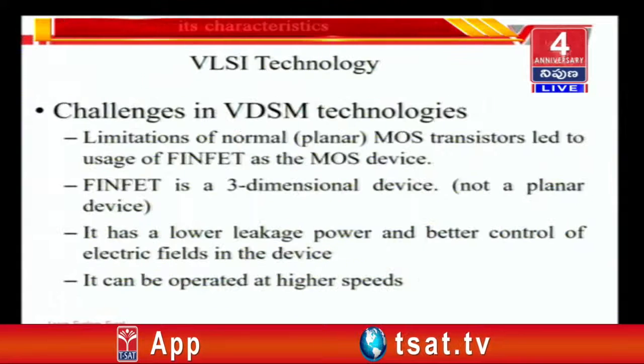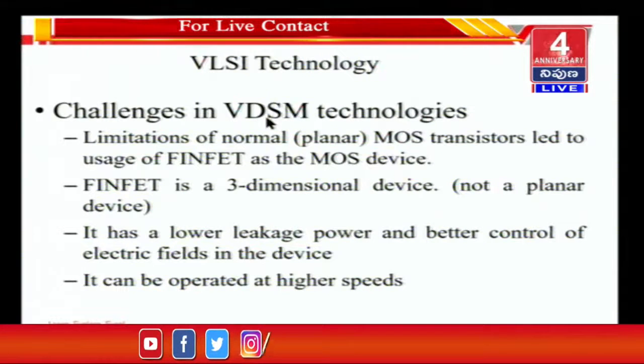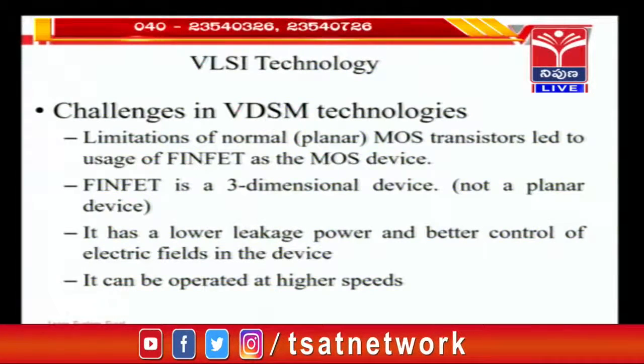Okay, moving forward. The challenge is in very deep submicron technologies. Deep submicron technology is basically technologies which are smaller than, previously they used to say, 0.25 microns. Deep submicron is up to 0.25 microns. Smaller than that, that is 130 nanometers, 90 nanometers, 45 nanometers. Now people are talking about 2 or 3 nanometers.